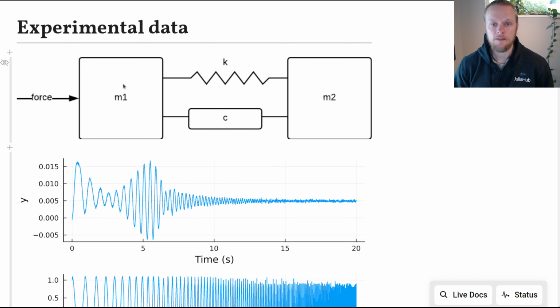So this is a very common model of position control systems where the first mass corresponds to the motor, and it has some inertia, maybe it's rotating. And then there is a gearbox or some other flexible transmission, and then we have the load mass, the thing we want to make move. All right. And since there is some flexibility here in this transmission, we get kind of a resonant system.